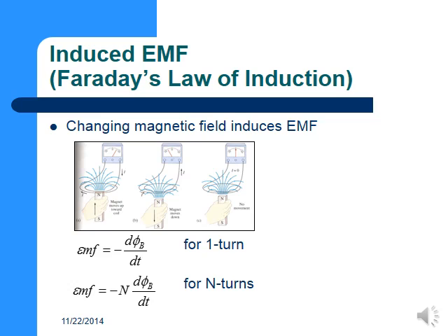And so this EMF is an electromotive force, or potential difference if you have terminals, and you would see it on a multimeter if you had the wires connected to a terminal of the multimeter as shown. EMF is equal to negative d phi dt for one turn. With multiple coils of wire, we have EMF is equal to negative N, the number of turns, d phi dt.